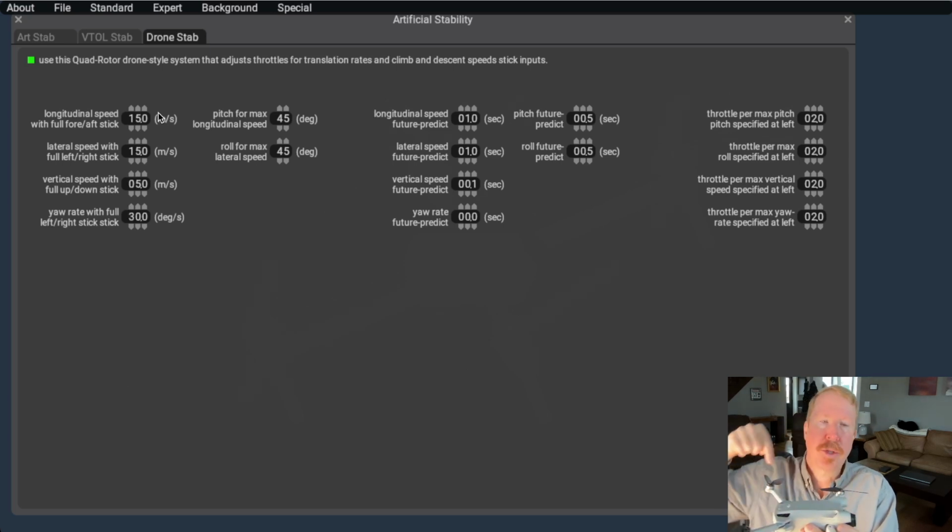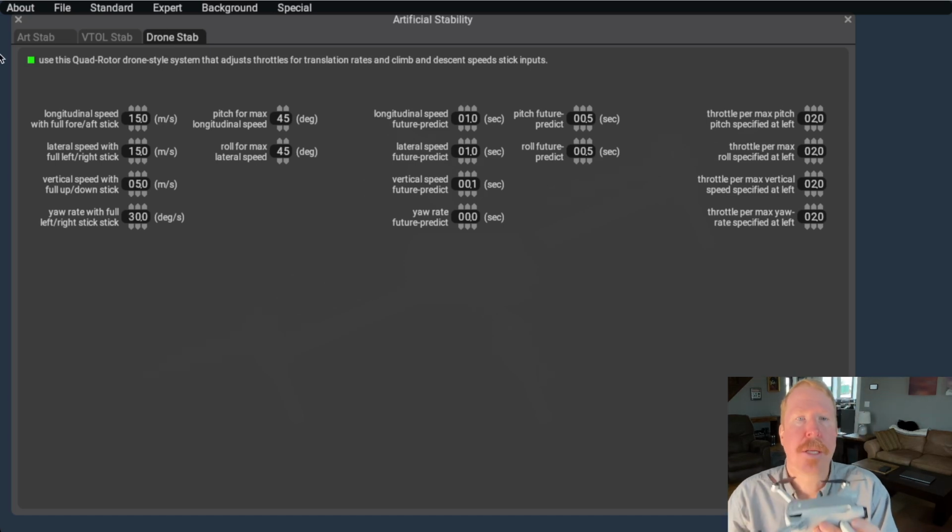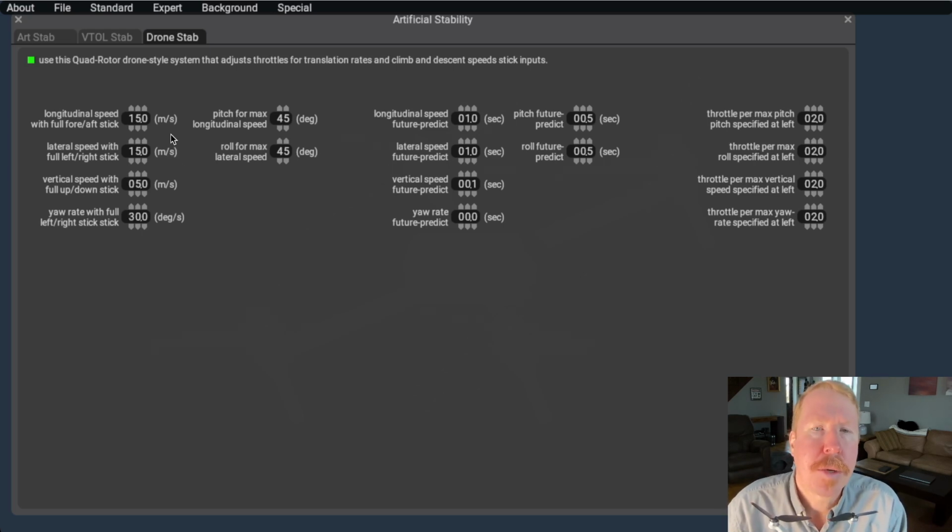And the way these props turn, clockwise, counterclockwise, if you just juice up the corners, counterclockwise and clockwise rotors get more or less lift, then you're going to yaw the thing as well. So that's how the flight control system is going to go from a commanded rate out to the rotors themselves. But the question we have to ask is, how much do we want to change the throttle, right? That's the question we still have to ask.